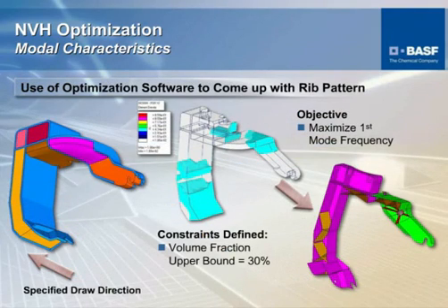We have a tool that actually goes back and, based on parameters that we input as far as the thickness and where we want it to optimize the structure, it can go back and tell us topologically what areas need most stiffness, so therefore remove material from it and just put the material where it's needed. And this is another powerful technique.